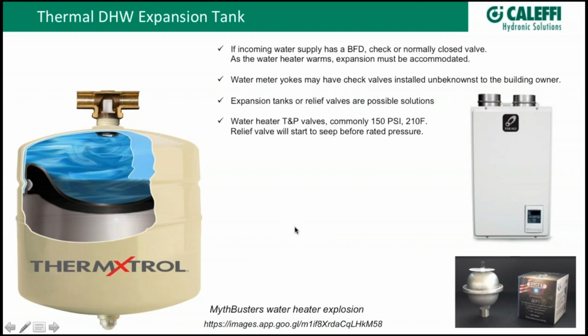Oh, perfect. Well, I just wanted to point out, too, that you talked about backflow prevention devices or check valves or a normally closed valve, but another thing to think about is that pressure reducing valves can cause a need for thermal expansion tanks as well, because in most cases those pressure reducing valves won't allow backflow, depending on the inlet to outlet pressures and things like that.